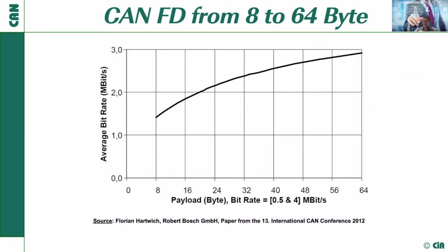Otherwise, if you're under this 1 Mbit, then in general, it's not that tricky to make the CANFD network run under all circumstances. But with regard to CANFD physical layer handling, we also have some other videos available on our YouTube channel, so maybe you'll find some further notes there, and I will say something about the physical layer later on. For the moment, I just want to say we have two features: the data field and the communication speed, which we can separately choose the right settings for our application.